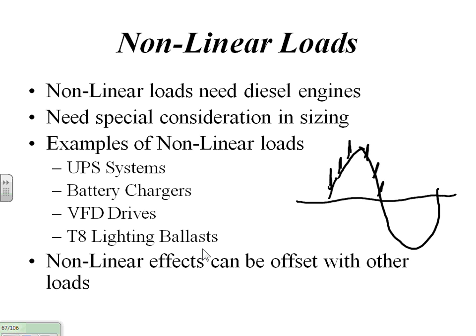Under normal circumstances without the notches, if it sees a drop in amplitude or voltage, that coupling back to the voltage regulator says, oh, we need more excitation. So it feeds more current into the exciter, and when that happens, we get the voltage back. Okay, part of the automatic voltage regulation.